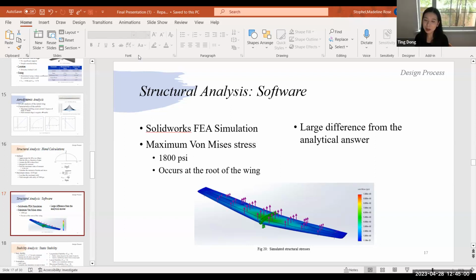Yeah, so what I mean is that since your hand calculation is based on the wing spar as the major load carrying structure, and the calculation focuses only on the wing spar, I would prefer to see you model it in the software using just the wing spar. Because in an actual situation, the skin really does not carry much load, especially in the first iteration where you use lightweight PLA.